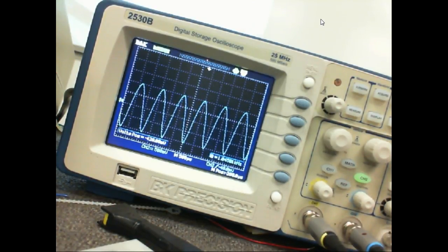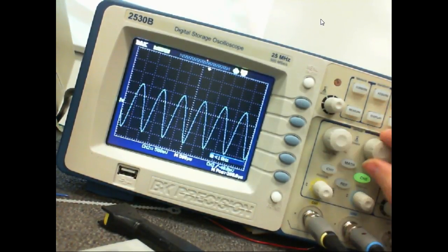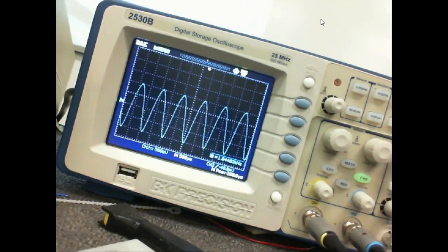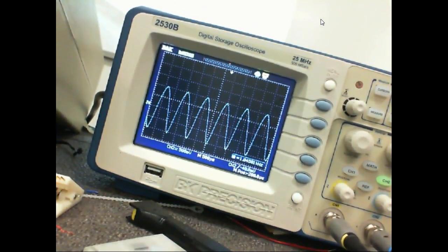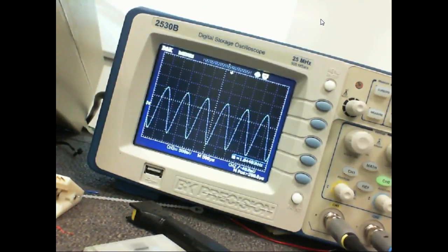Because what we're going to do now is start adjusting this until it drops down to, what's 1/2 of 4? So that's 4 volts. We're going to adjust this resistor till it drops us down to 1/2. As soon as my output drops to 1/2, because the gain is fixed, right? We're not going to try to do this on the input because we'd be dealing with 10 millivolts on the input. But the gain is fixed at 77. Okay, you understand that? So I'm looking at the output where I've got that gain. So now instead of trying to deal with 200 millivolts, I'm dealing with 4 volts.